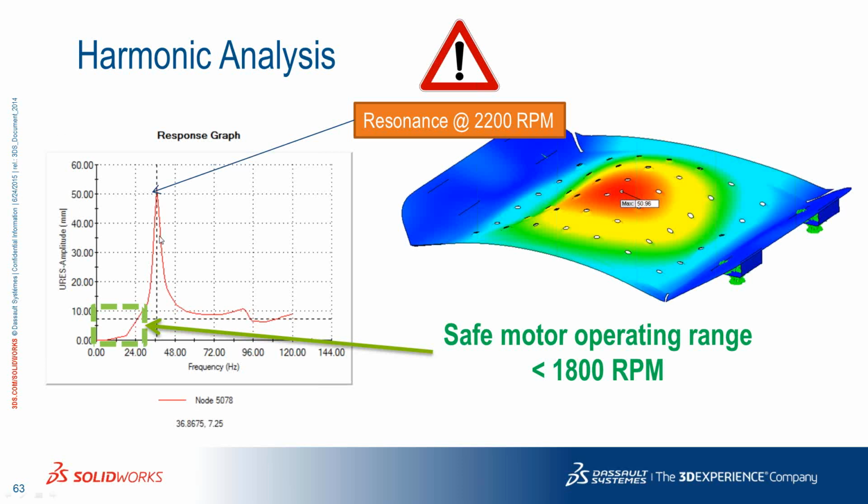If I cannot change the working RPM of the motor, then the next step is to try out multiple design scenarios, different design cases, and see what design case is probably going to give you an amplitude that's acceptable. Maybe you're looking at keeping the displacement of this platform to less than 20 millimeters or 30 millimeters, and so SOLIDWORKS simulation vibration analysis can actually help you out there.